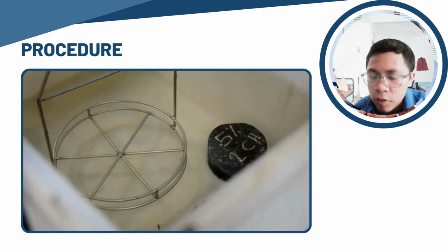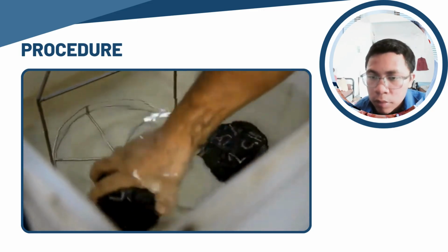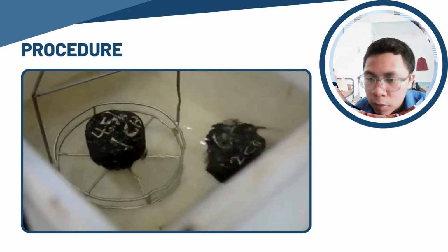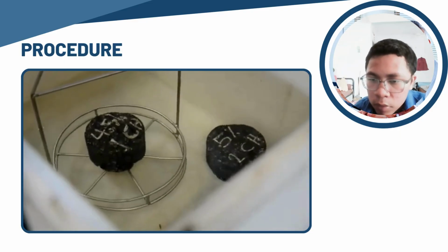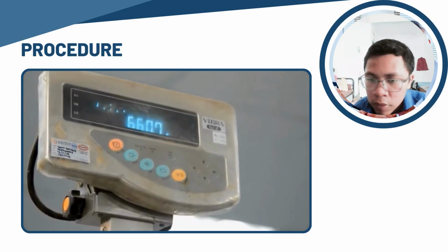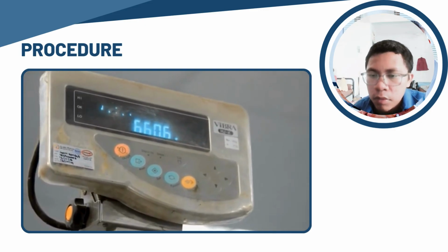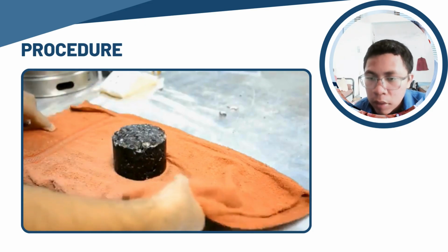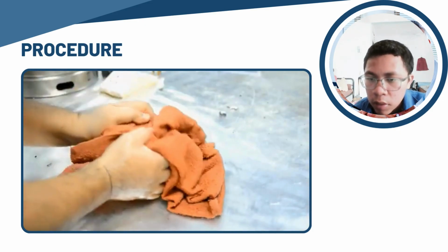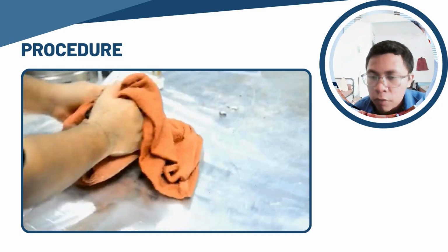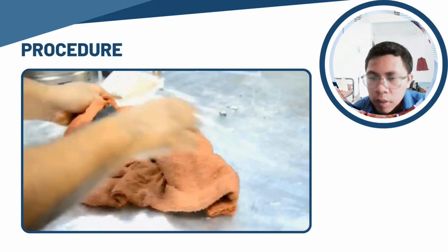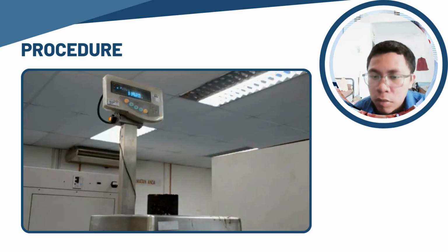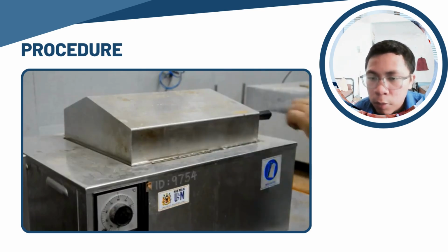Next, use the heated spatula to roll the mix vigorously 15 times around the perimeter of the mold and 5 times over the interior. This process ensures a smoother specimen and eliminates any bridging of the rock. Next, compact the mix carefully using the Marshall compactor for the proper number of blows as